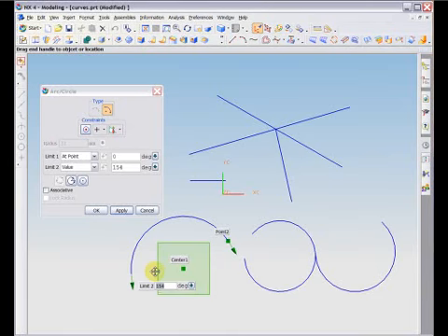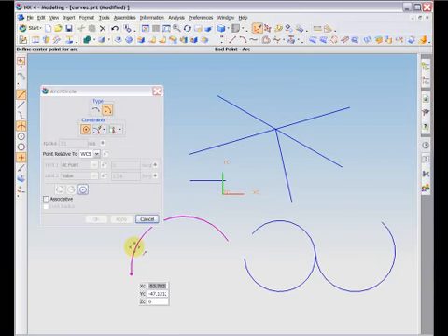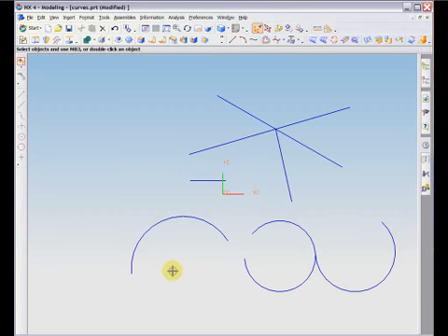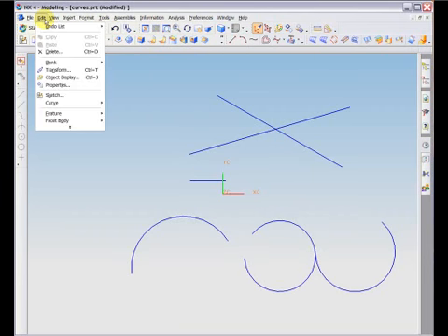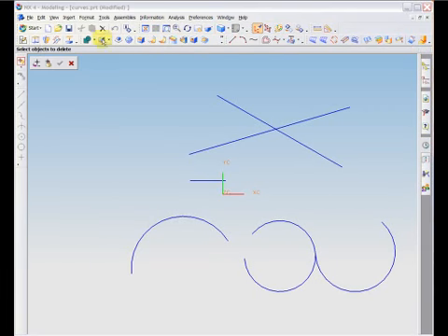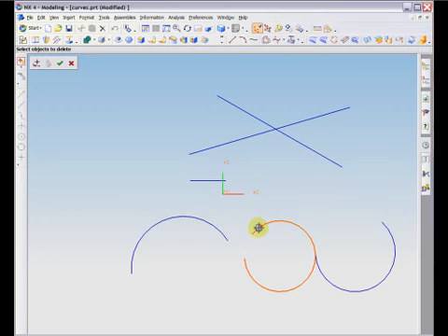There are several ways to delete curves. One option is to pick the entities you want to select first, then choose the Delete icon from the menu bar. This deletes objects immediately. Other options are available by going to the Edit menu, or by choosing the icon in the taskbar while no objects are highlighted. You can then choose entities you want to delete and click the green check to delete them. Note that the red X cancels the command.